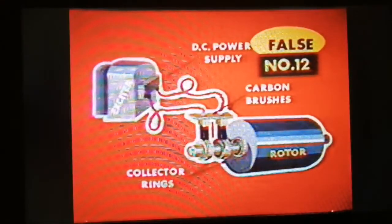Just because the AC rotor is not moving does not mean the exciter can't energize the field, so number 12 is false. In fact, there is danger of great heating damage to the rotor if the exciter does apply voltage to a non-moving coil. 13 is false. A reserve exciter can be used with any generator where DC requirements of the rotor coils can be met by a reserve unit.